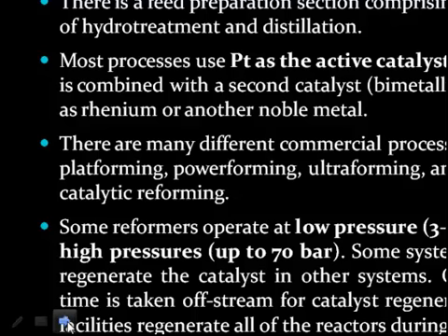Some reformers operate at low pressures, 3 to 13 bar, others at high pressures up to 70 bar. Some systems continuously regenerate the catalyst. In other systems, one reactor at a time is taken off stream for catalyst regeneration, and some facilities regenerate all the reactors during turnarounds.